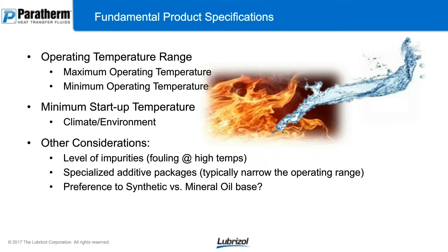The reason why minimum operating temperature is so important is because that comes into effect with efficient pumpability and fluid movement to allow for heat transfer at that temperature. Maximum operating temperature is more about thermal stability and making sure you don't overheat the fluid.